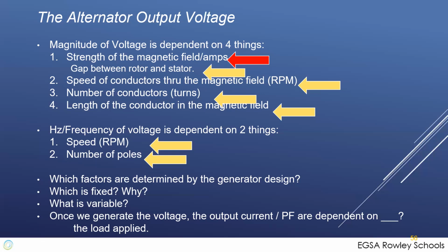So you have to explain that all we can do is produce a voltage, and that sine wave is generally pretty pure. There are things that go on, such as winding pitch, that vary the shape of the waveform slightly, but generally it's a solid waveform. The impedance of the generator is different than the impedance of the utility transformer, and that can lead to differences. But all we can do is produce a voltage, and you have to find a nice way to tell the customer that your power factor is what you're doing to the voltage we produce. That can be a difficult discussion to have sometimes, especially with the cost to correct some of these power factor and power quality considerations.